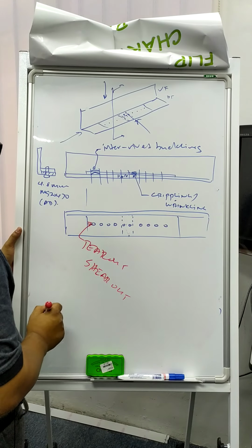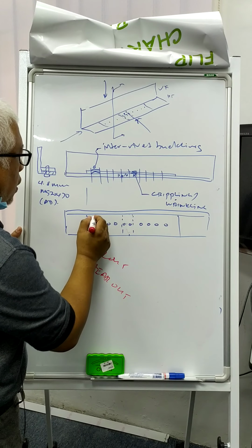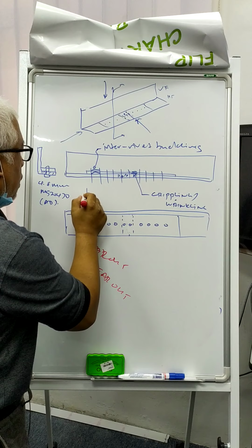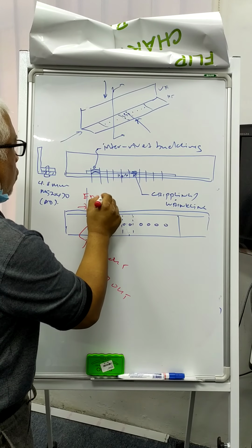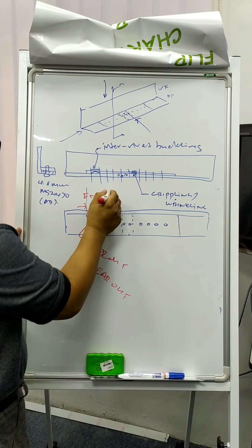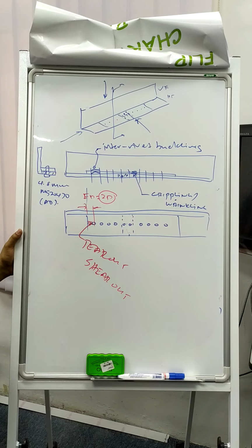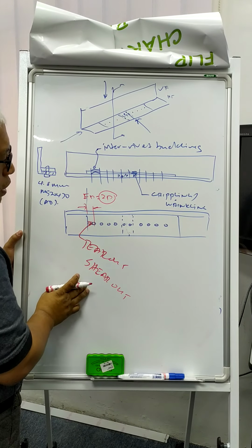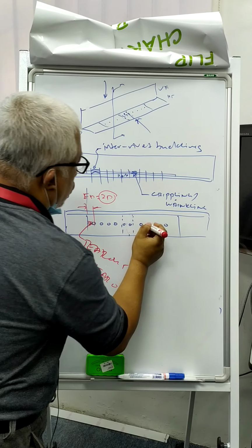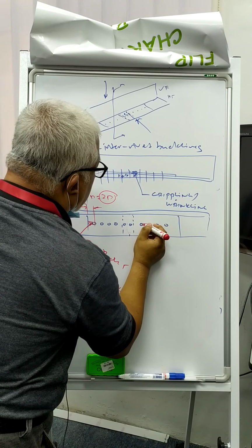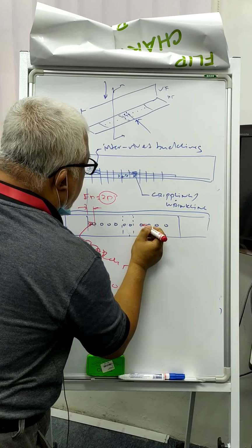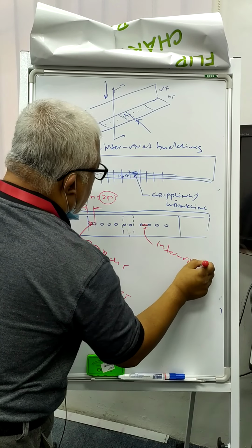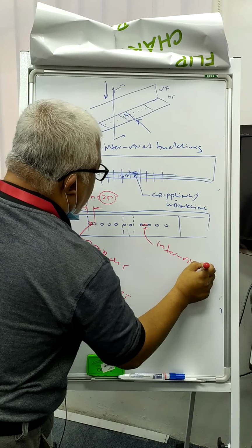That's why the rule of thumb, the edge distance, okay, we have edge distance, rule of thumb is 2 times the diameter. So why we need to use 2 times the diameter, hopefully you will not have the problem of tear out or shear out. You also may have damage from rivet to rivet, we call it inter rivet shear.